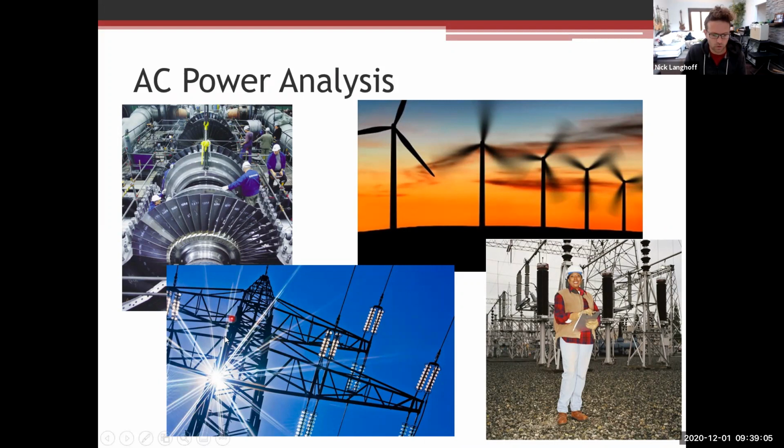So you've seen transformers, things like this, like at power generation stations. What they allow you to do, one of the things they allow you to do, is increase the voltage by a factor of 10 by decreasing the current by a factor of 10, let's say, which ideally ends up having the same amount of power transfer, right? Increase the voltage by 10, decrease the current by 10, and you have the same amount of power. They're just scaled by a factor.